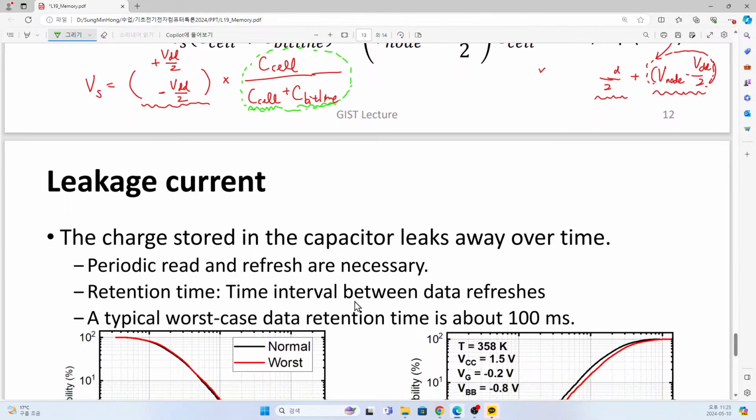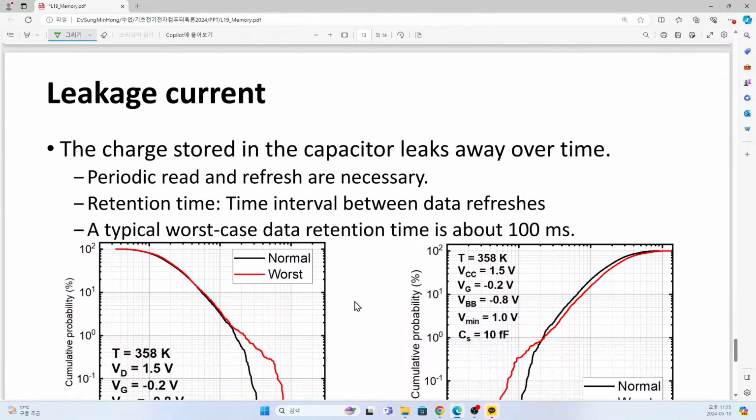And I think that it is the last slide I have prepared, but this is just repeating our previous discussion. In the case of leakage current, why is it important? Because in the case of our DRAM, first we write something, so logical number 1. After that, the time for this charge to completely disappear is solely determined by this leakage current.